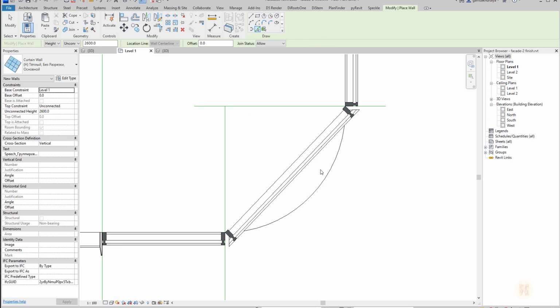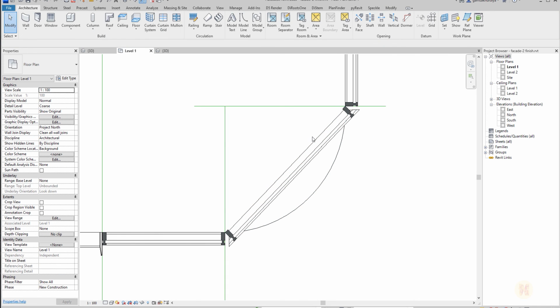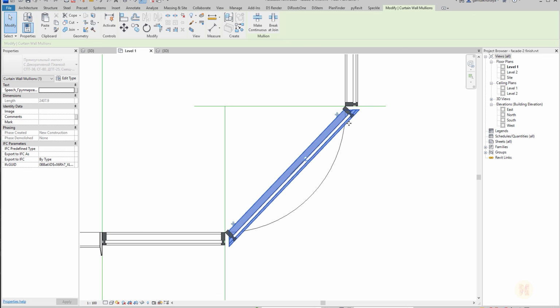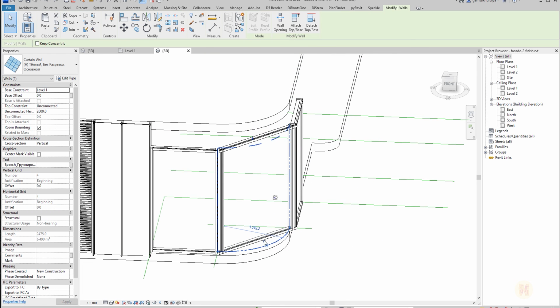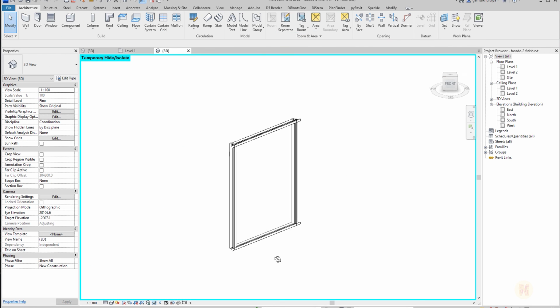Okay, we get the model, but this looks so terrible. So what we can do, as I said before, this is a misclick. You can actually create, as I said, the wall instead of the panel, but we will use the panel. We already have this panel inside our project, so what we're gonna do, just let's go to the 3D view. I will select my wall right now and I will isolate it. I isolate this element, as you can see.